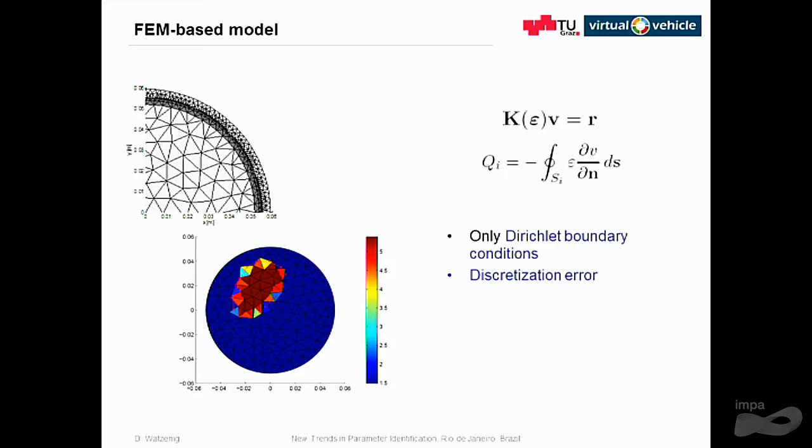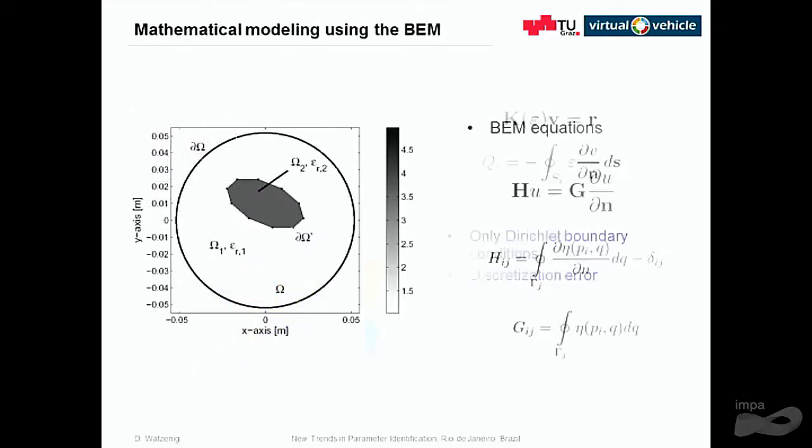And at a certain stage, if you're below the measurement noise in the error, it doesn't make sense to increase the number of finite elements, because the measurement noise is canceling out this effect. You're thinking that you're getting better, but in fact the measurement noise is your lower bound. And for the previously mentioned setup, we are actually measuring and using the charge. So it's based on measuring the displacement currents. And basically, we are integrating the charges out of it, and they are used for the reconstruction.